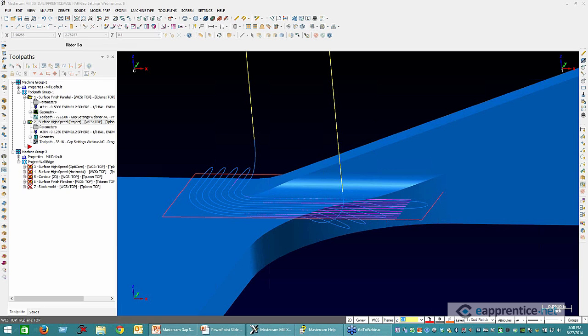Yes, what's going on there is that the tangential options, when you're coming off of a set of surfaces like that, can't always figure out exactly what the right motion is, and a lot of times it's trying to approximate not only the tangent extension, but then the smooth settings on top of that. So what happens is part of the motion gets defaulted to broken.